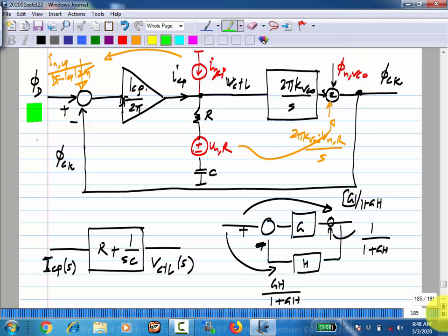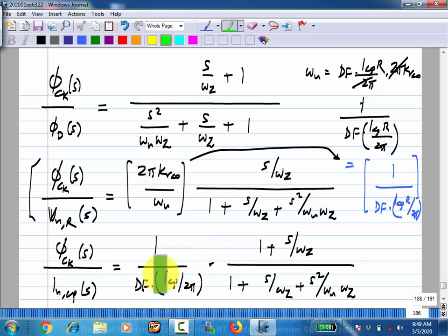So this is high pass. What it means is any low frequency phase noise of the VCO, right? That's okay. That will get corrected by the loop. Whereas at very high frequencies, if it is jittering around at very high frequencies, nothing can be done. It just comes straight out. Okay. This is fine. And then the other two are essentially related to this.